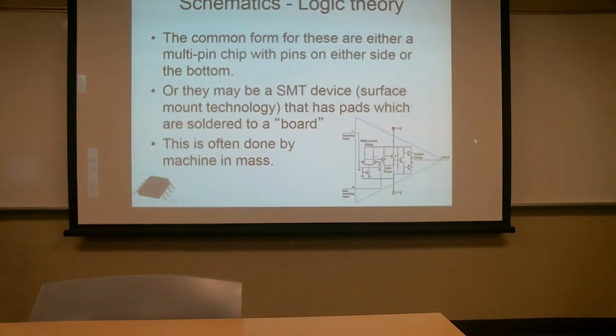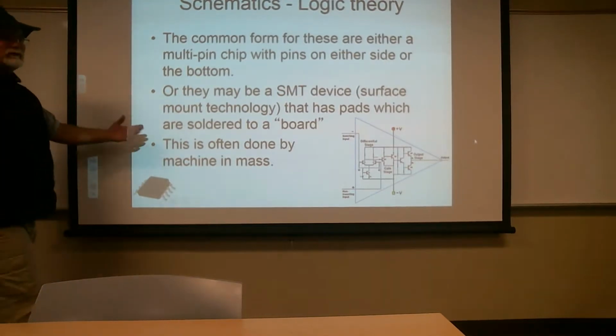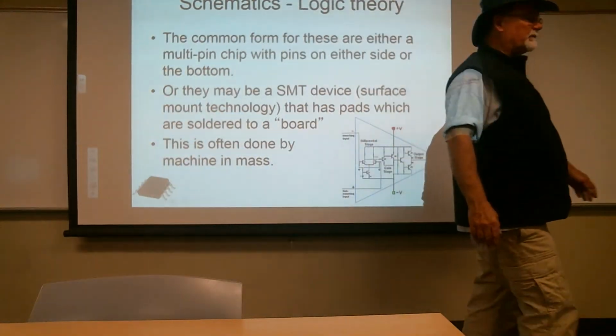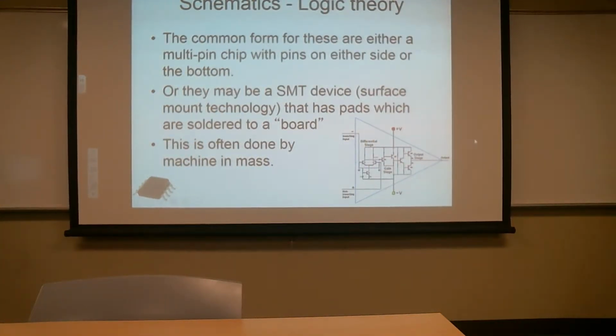Now, in this particular one, most of these are going to be multi-pin, either 8-pin, 16-pin, or a whole variety of different counts. Sometimes they have 10-pin. There's a few 4-pin, but most of the time, if they put multiple units into a single package, and you don't need it, it's still soldered down, but the trace doesn't go anywhere. It doesn't do anything. They may be socket mounted, where you solder a socket in, and the chip goes into the socket, or by solder wave technology, they may do other means of surface mounting them.